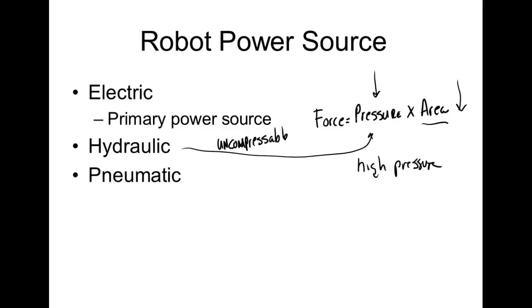Pneumatics, as soon as it starts moving, it wants to uncompress. So what happens is that when it hits against the actuator, it's going to be jerky, right? It's going to create the pressure, the thing's going to move, and then what's it got to do? As soon as the actuator moves, it's got to come in and hit it again.